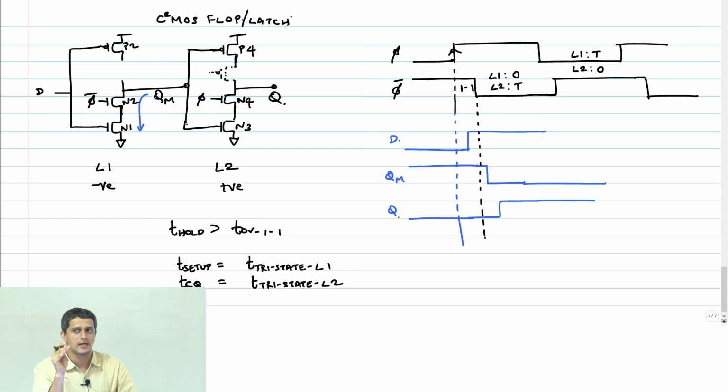What do I mean? It doesn't mean that both overlaps are not an issue. One overlap is still an issue, but I can alleviate that by imposing a hold time constraint. It's always the other overlap period that's a problem, and this flop is insensitive to that overlap. The non-sampling edge overlap is not an issue.